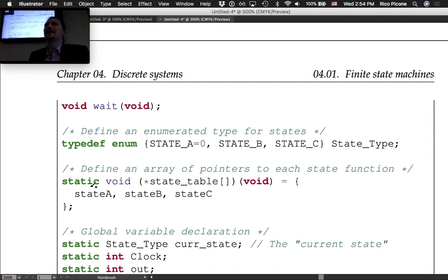So you are actually going to calculate how long the wait function should take, counting the number of processor cycles it should take to do each instruction on the processor. But how do we know how many clock cycles it takes? We'll talk about that. It's described in a specific manual that I give you a link to. It's pretty much an exercise of looking things up, though you have to do some interpretation in the manual because there's a lot of variation for each instruction.